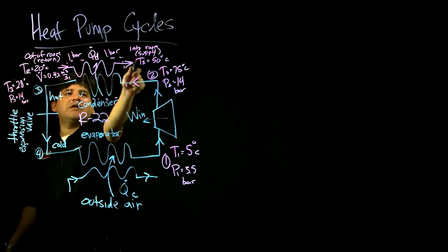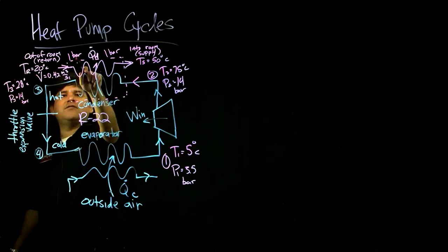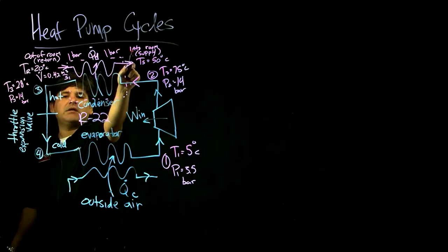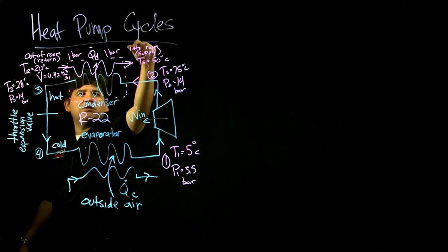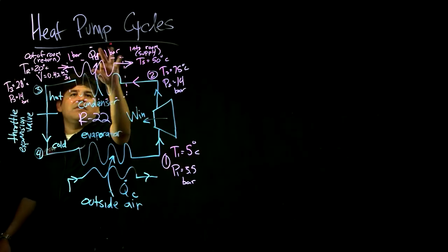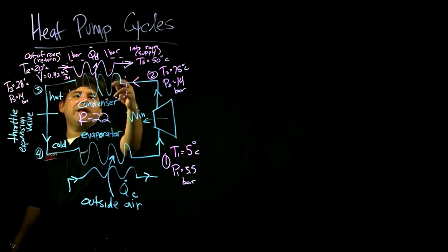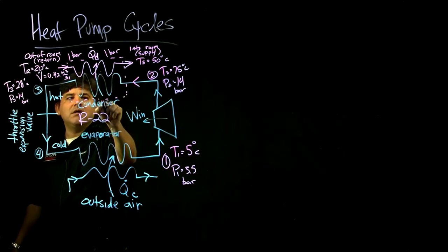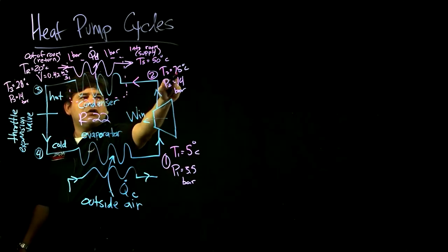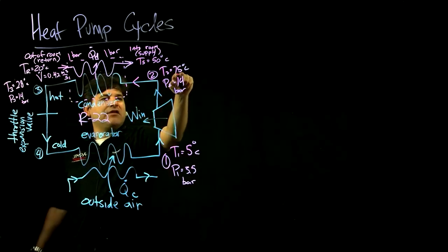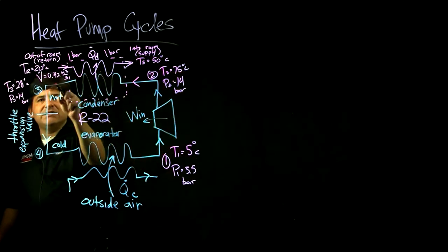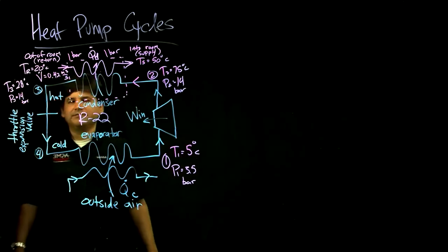Let's just neglect any pressure drop of pumping, of flowing through the ducts of a HVAC system, heat pump system. So this is going to be 1 bar of the room coming in, flowing into 1 bar of the room to supply a higher temperature air. That's the heat exchanger. How does that get hot? It gets energy from the refrigerant at the condenser stage of the heat pump cycle. It starts off as the refrigerant is 75 Celsius, loses energy, condenses to 28 Celsius liquid.